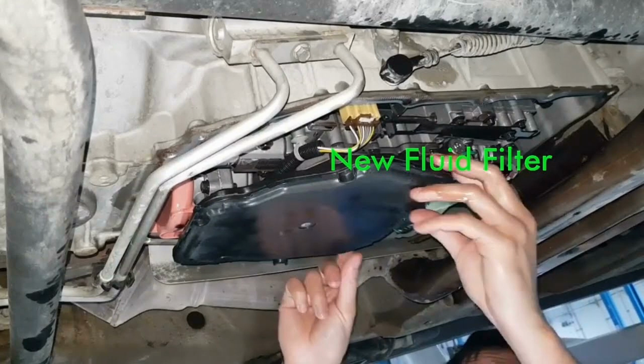4. Transmission overheating. Transmission overheating may be a symptom associated with code P0711. Due to incorrect information transmitted by the temperature sensor, the transmission system may not be properly regulated, possibly leading to a rise in transmission fluid temperature.